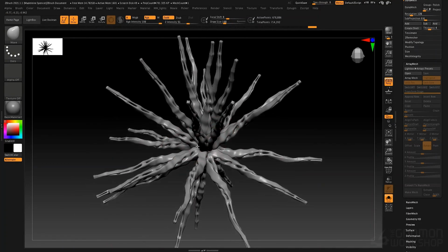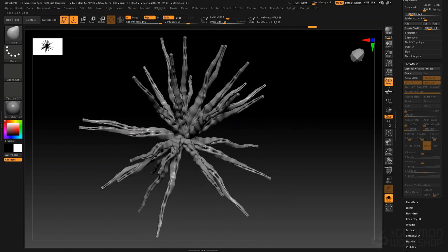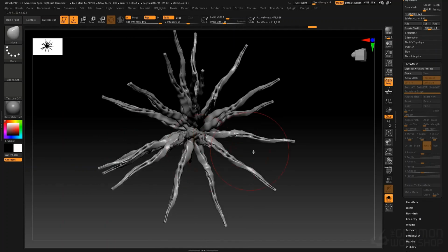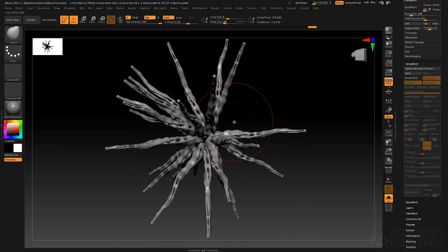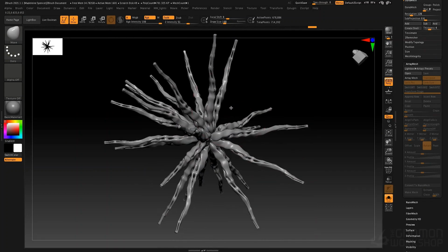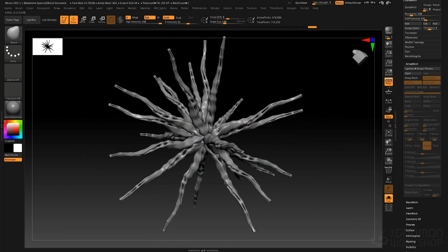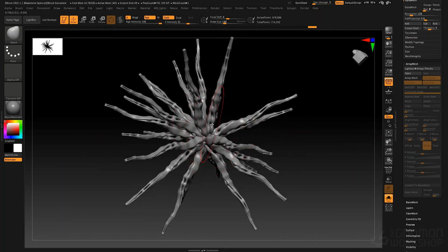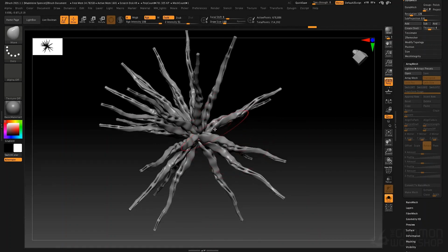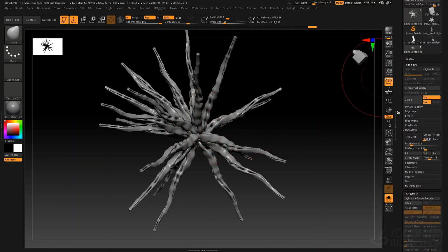There's many reasons why you would want something to be a single object instead of a whole bunch of objects jumbled up together. And of course, you could accomplish something similar by dynameshing them together or remeshing them together with Z-remesher once they are joined as they are now. If I Z-remeshed these when they were still separate pieces, each individual piece would get its own Z-remeshing. They would not join together. So that is using extrude to actually join your instances, to extrude your instances out along that curve.